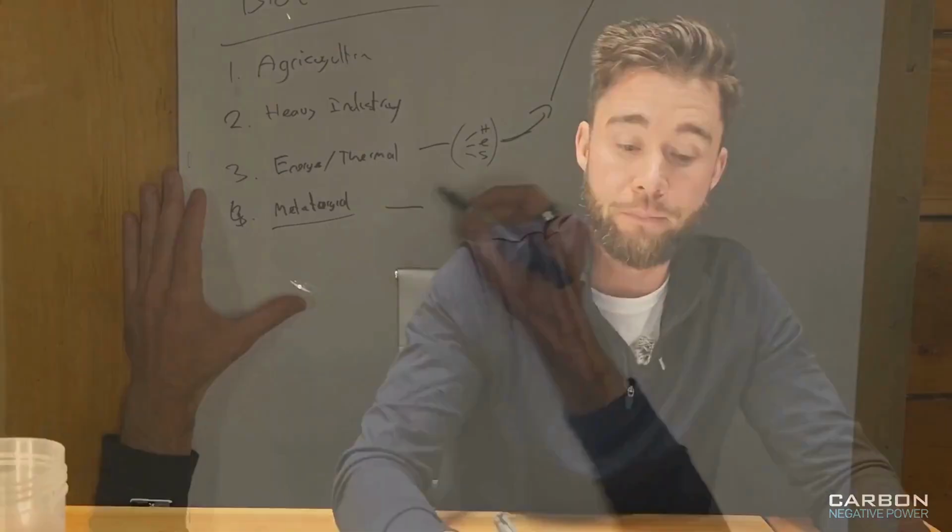Metallurgical, this is where we're using a much higher grade of biochar, similar to what we're producing here, but it's used as the reductant in, say, steel making or magnesium production or even lithium production. They all use carbon as a reductant. That reductant is purely just a way to take oxygen out of the finished metal before it's finalized. So it's a very high quality of carbon. Currently the industry uses coking coal, or maybe recarburizer are some of the different terms for it.